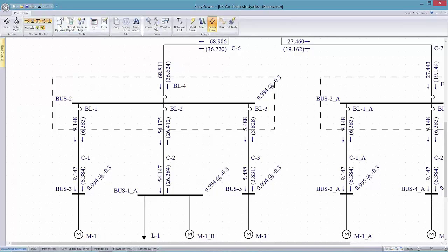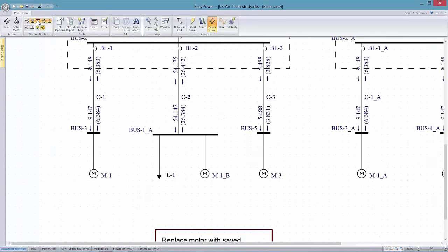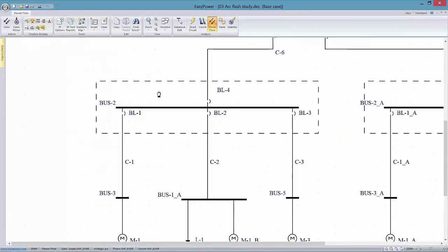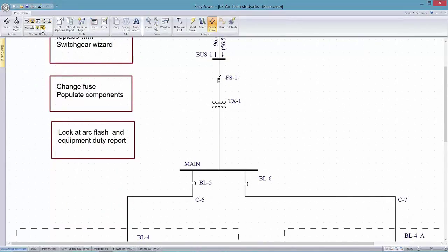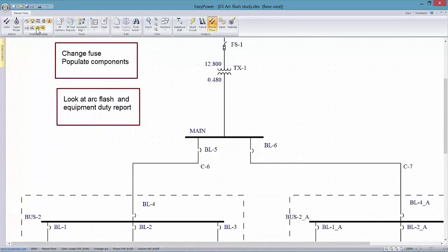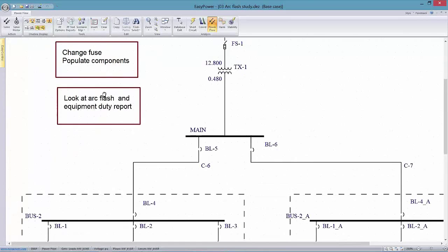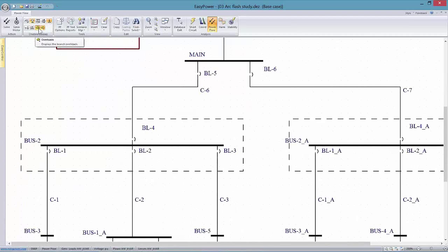Okay, so that's what we're looking at here is the voltage on the bus. As I click on the icon, you can see the voltage appear and disappear. We're looking at the motor and load data. Here's the branch flows, the transformer taps, which if we come back up here, turn those on, we just have a straight 12.8 to 4. Then we have the ability to invoke overloads, and where we see anything that's exceeding the branch currents or the voltage violations, they'll highlight in red.